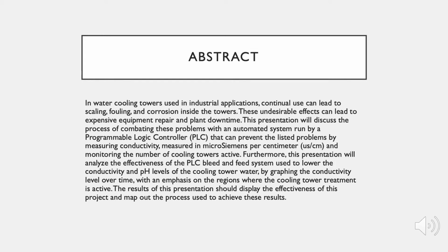In water cooling towers used in industrial applications, continual use can lead to scaling, fouling, and corrosion inside the towers. These undesirable effects can lead to expensive equipment repair and plant downtime. This presentation will discuss the process of combating these problems with an automated system run by a programmable logic controller that can prevent the listed problems by measuring conductivity, measured in microsiemens per centimeter, and monitoring the number of cooling